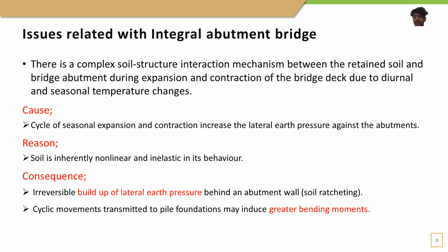Because soil is inherently nonlinear and inelastic in behavior, after a number of cycles the soil properties will start to change and they won't regain their original properties. Also, because of the cyclic moment transmitted to the pile foundation, it can induce greater bending moment in the integral abutment.